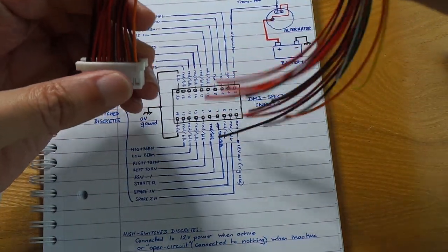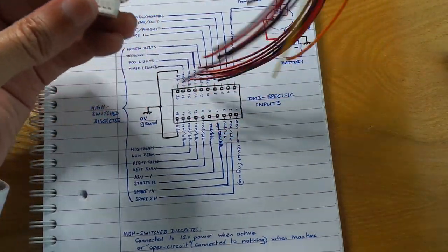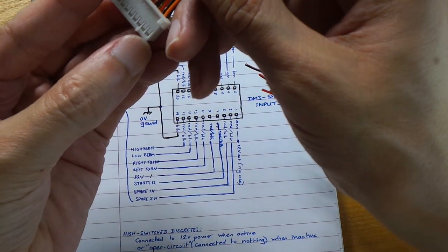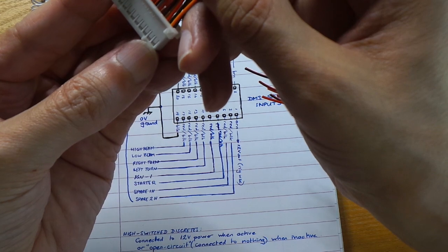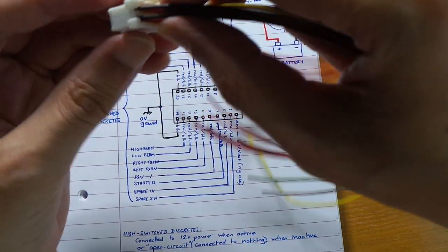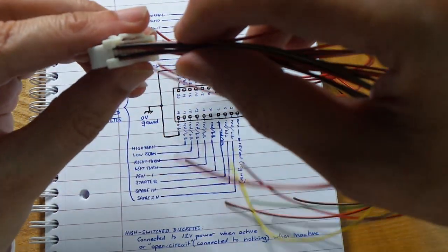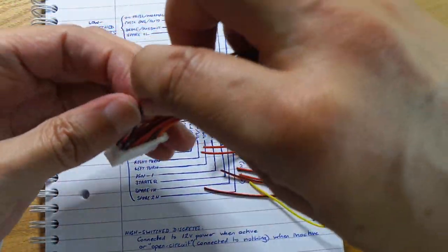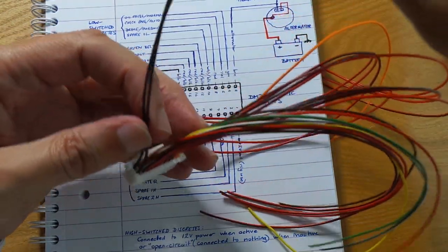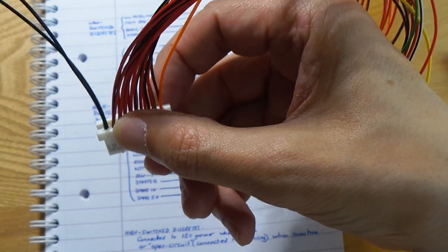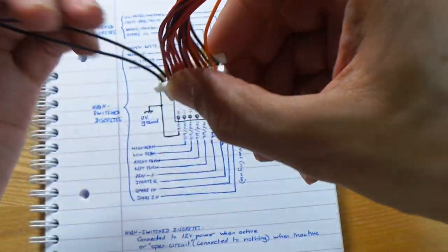In the real car you probably won't need this connection, so I suggest this one you do actually remove, again just by raising this small plastic tab and pulling the wire out. Similarly, pins 19 and 20 are black wires, and those are ground connections. Again, you won't really need those unless you're using the unit on a test bench, so you can either tie them back or you can remove them, as mentioned earlier.